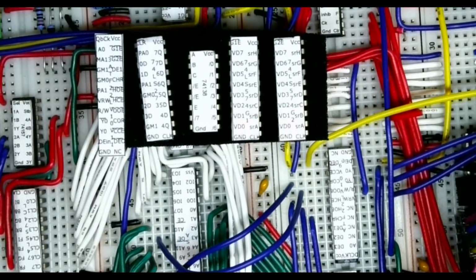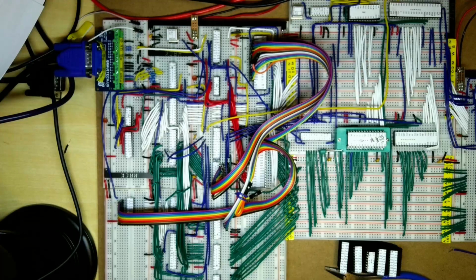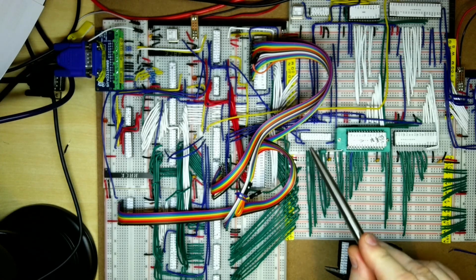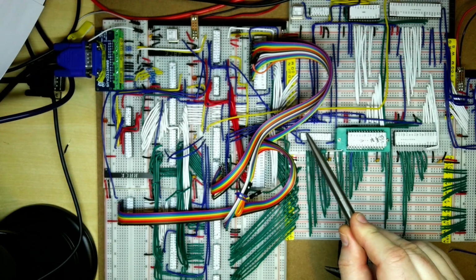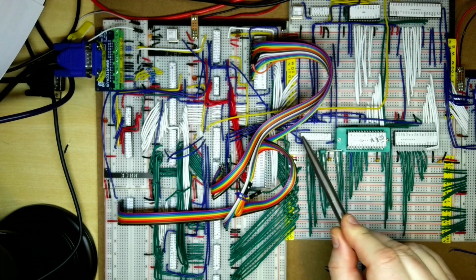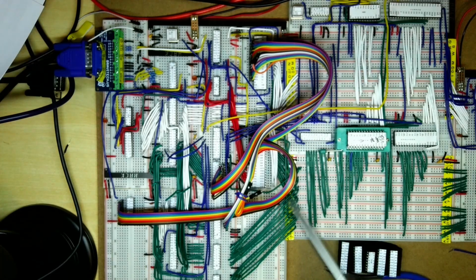I'm now going to take a look at the board layout and see what we need to do for that. So this is an overview of the video card that we had last time. We haven't really got enough space for adding the address decoder up here. This is the current PLD that does the address decoding. So I was going to put the address decoder in there, followed by the page latch, page register. So this is going to go down here.